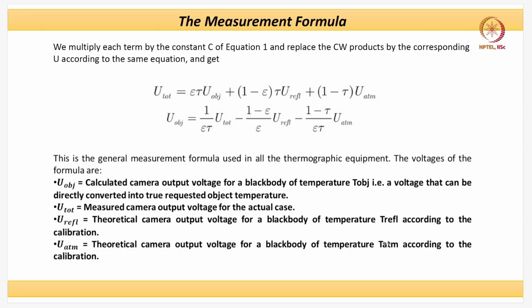But you cannot do it, for example, in a highly fluctuating environment, like a turbulent flow or a turbulent flame, because it is simply not possible. It's simply too onerous to calculate the temperature in those kinds of systems. So you can utilize it for film cooling, pinned heat exchangers, droplets, and surface temperatures in applications like batteries or thermal management tools. In those cases, I think this will be highly, highly useful, but it would not be useful in all the cases. That is the whole point.